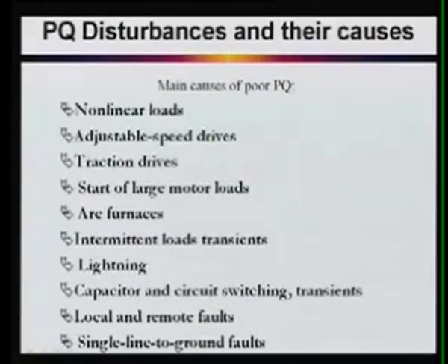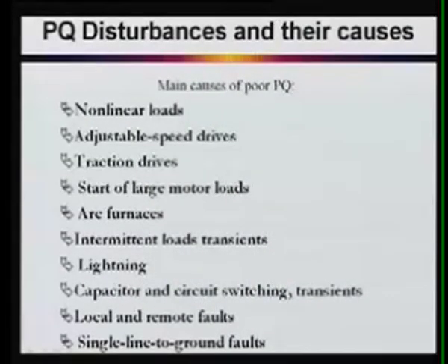Capacitor and circuit switching transients. If your capacitor is switched, normally they are in the distribution system. The switching instant is very, very important, and you don't know at which instant you are going to switch. Because capacitors store energy and we have the inductor in the circuit, there may be RLC resonance and other things. So switching your capacitor and the circuit, meaning a line, etc., switching in and out, will create some power quality disturbances, and they normally lead to transients.